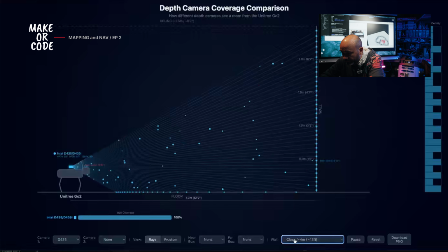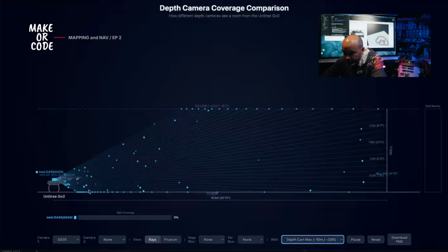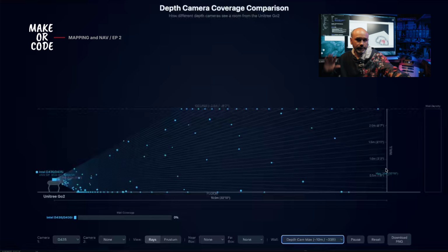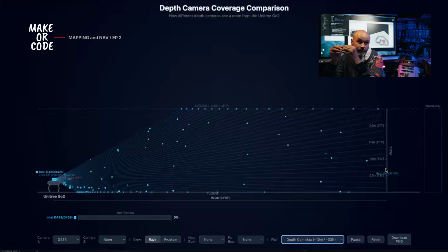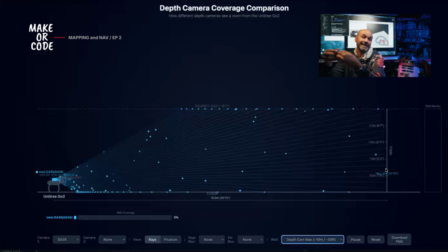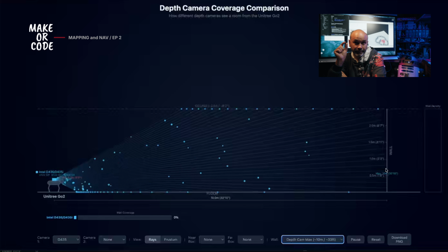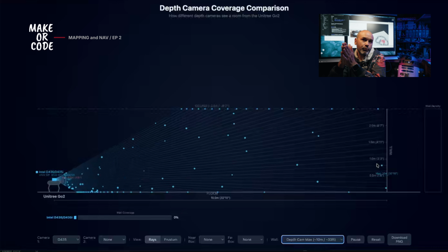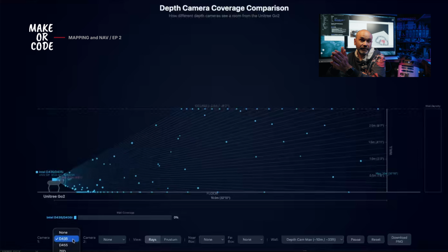If I then go further out, say 10 meters, the D435 is right at the edge of its limits of what it can see. So with the LiDAR, I could see out 10 meters, no problem. With the D435, 10 meters is basically where I cannot see anything anymore. I cannot see past 10 meters. And even at that 10 meters, the simulation here says you won't even see the wall at 10 meters away. It's like 9.8 or something. Okay, so what about then the D455?